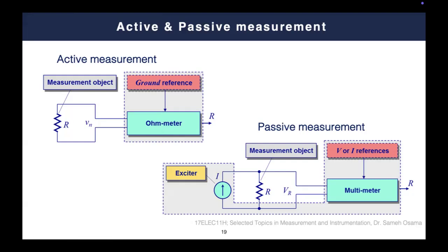So basically, based on Ohm's law, we know that the resistance value can be measured by applying a potential voltage here, and due to this potential, current will move. Then you calculate the value of voltage, the value of current, you divide the voltage over the current, then you get the resistance. This is the basic understandable way to measure resistance.